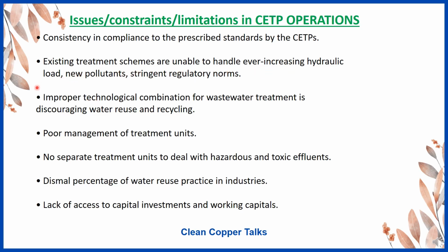Existing treatment schemes are unable to handle the ever increasing hydraulic load, new pollutants, and stringent regulatory norms. So the problem is, if you have designed a CETP based on some particular wastewater characterization, now after some years, say the participating industries have changed or increased, so the hydraulic load will increase. Hydraulic load is the amount of water coming. Don't confuse it with the organic load. Organic load is something else.